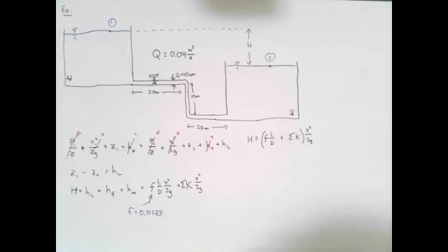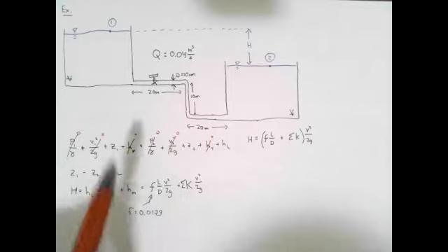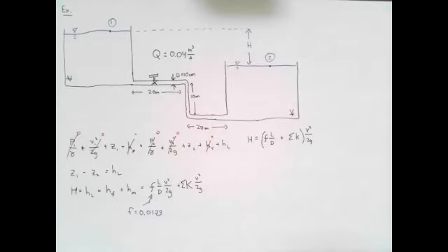Now let's go at this last term, the minor loss coefficient. The sum of the minor loss coefficients corresponds to any place where there is a change in your system. Normally, these are values that you're going to look up. There are tables that have different coefficients for different types of fittings. But instead of giving you those values directly, I want you to give it a try at identifying those places where there are changes in the system. So, Jessica, why don't you try to identify some of those components? Where do you think there are losses in energy in the system?